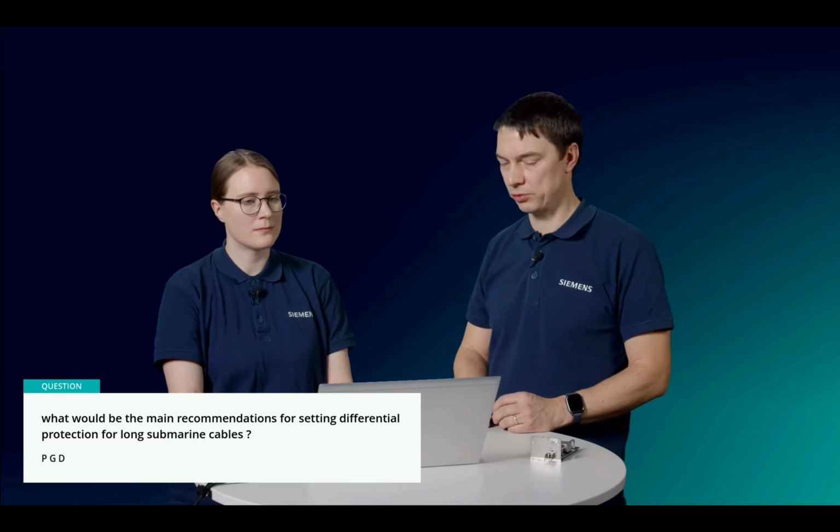Yes, in this case, you will need VTs at both ends. If you have these available, then you could also use the capacitive charging current compensation to increase the sensitivity towards the fault current. Maybe it's worth to do this. You don't write here what the length is, but I think this is not the limiting point because the cable will not be so long. Otherwise, you will need some compensating transformers in between. Yeah. Good one. Okay.